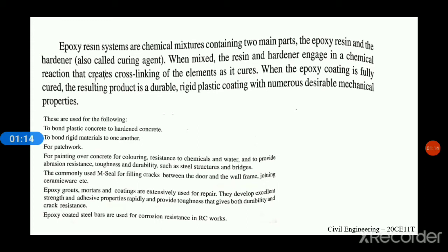The common epoxy resins are glycidyl ethers of alcohols. Liquid epoxy resin is diglycidyl ether of bisphenol A, and it accounts for more than 75% of the epoxy resin used in industrial applications. The low viscosity resin can be injected into small cracks, whereas the high viscosity materials are used as a binding agent for filling larger holes and cracks.